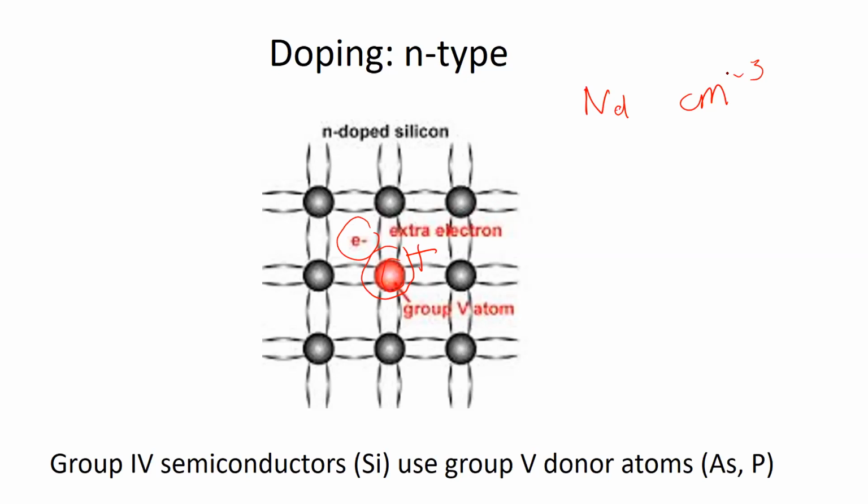Now, once the semiconductor is doped, as it is here, we refer to it as extrinsic, because it's no longer pure or intrinsic. The process for generating additional conducting electrons is very effective, and so we can introduce a large number. In fact, the concentration of electrons introduced from doping is far larger than the concentration of conduction electrons present in the intrinsic semiconductor because of the difference in band gap.